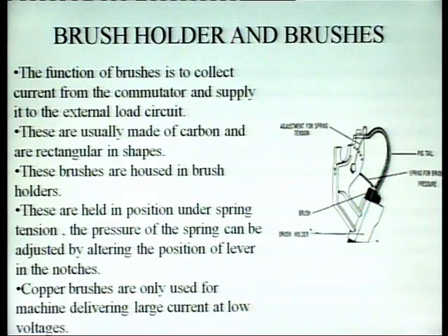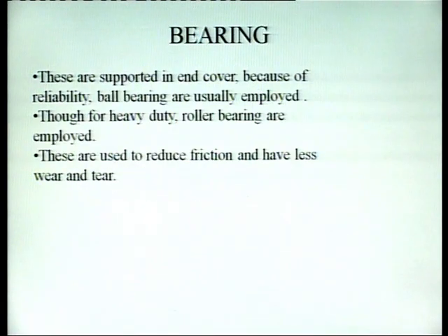These brushes are housed in a brush holder. These are held in position under spring tension. The pressure of the spring can be adjusted by altering the position of the lever in the notch. Copper brushes are only used for machines delivering large current at low voltage.